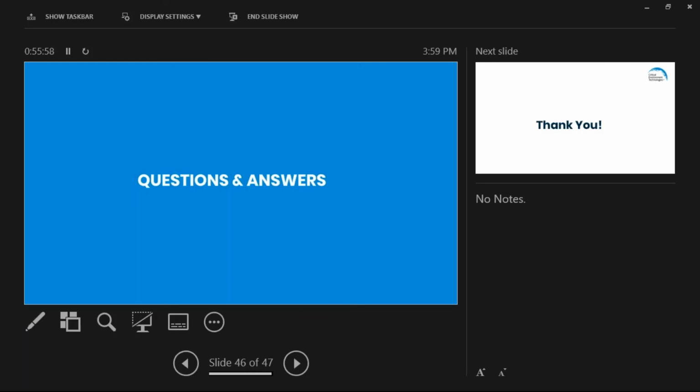So I think that was a very good long response, but I think the answer where to locate it is 3 to 4 feet above finished floor. Is that correct? Both CO and NO2. Yes. Okay. Yes, no question. Yeah, because you want it in the breathing zone to protect the occupants. You want to protect the people. That's exactly right. You don't want to protect the ceiling.